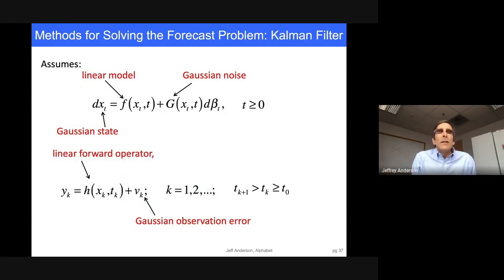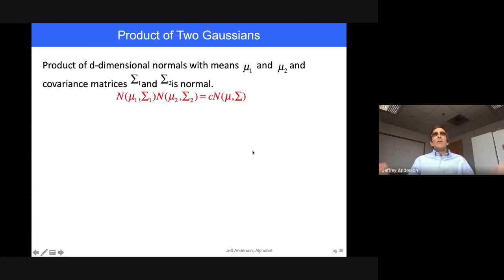The Kalman filter is another classical now method out of the early 1960s. If we go back to the equations we had, the Kalman filter makes a number of assumptions. This is related to the second question. It assumes that the model is linear, the deterministic part of the model. It assumes that if there is a stochastic part of the model, that it is Gaussian. It assumes that the state is Gaussian, and this was specifically, I think, what the questioner was about. It assumes that this mapping that gives you an estimate of the observations is linear, and it assumes, as we already did for this presentation, that the noise or uncertainty on the observations is Gaussian. If you do all that stuff, it turns out that long before Kalman, Gauss knew about this. He just didn't have big enough computers to make it worthwhile.